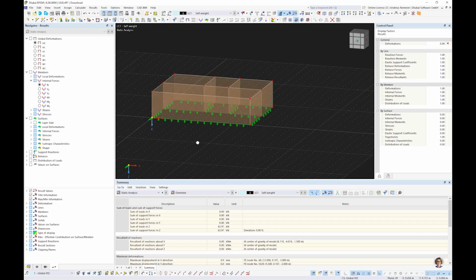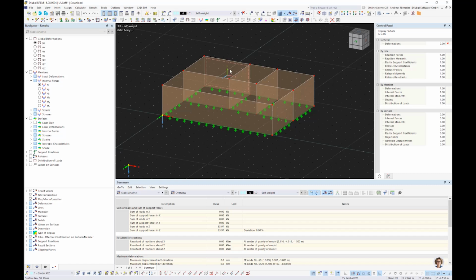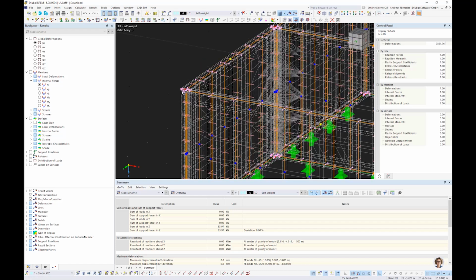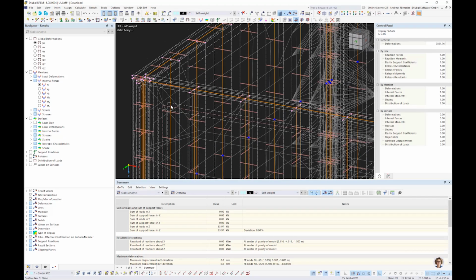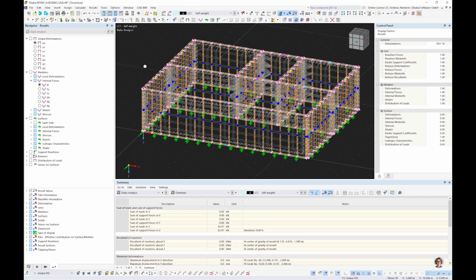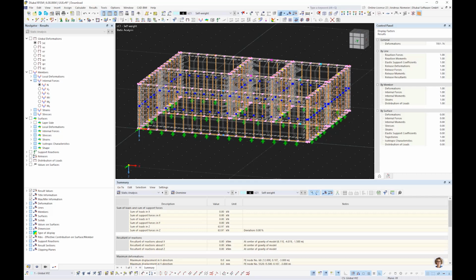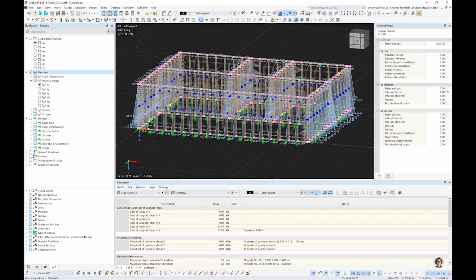Why? Because behind these surfaces we have substructures. We have here, let's say, beams with surfaces, with springs. So there's a really complex model behind, and we defined it only via surface. Yeah, and you can calculate it. And if you watch the forces, these are the normal axis force in the member, how the normal axis force increases. Of course, you have to take more care about loading, but you see, you get a calculable model with this substructure idea. Yeah, and you don't have to model it by hand. We only copied surfaces.